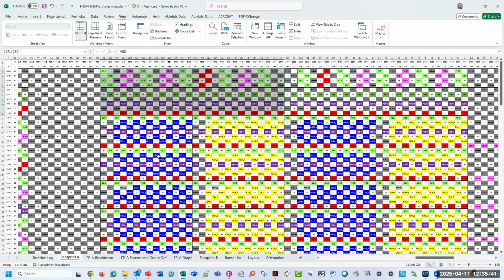And maybe it's a die on top of a die with no interconnecting layer, because the bumps on the bottom side of the top die match exactly the bumps on the top side of the bottom die. In which case, it's a die-to-die direct connection without an interposer.